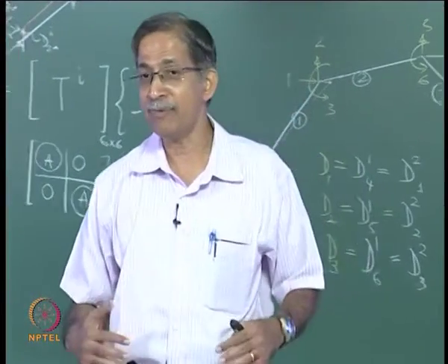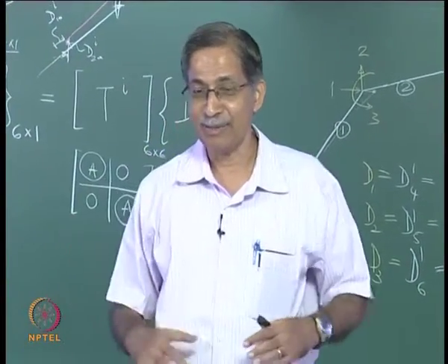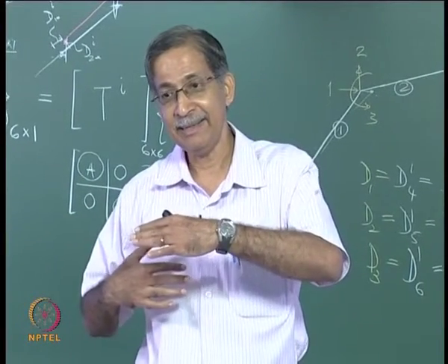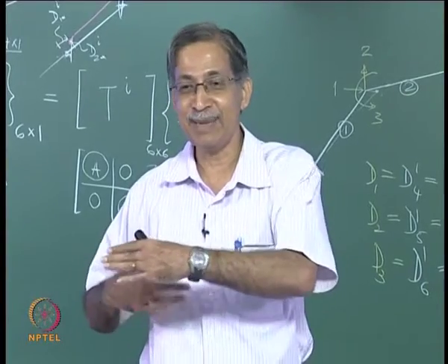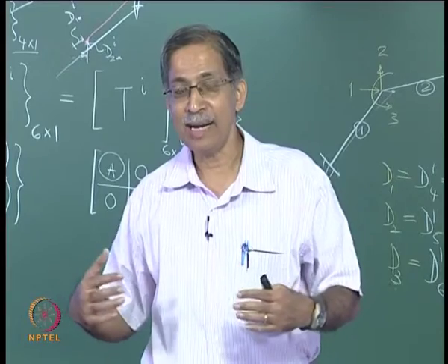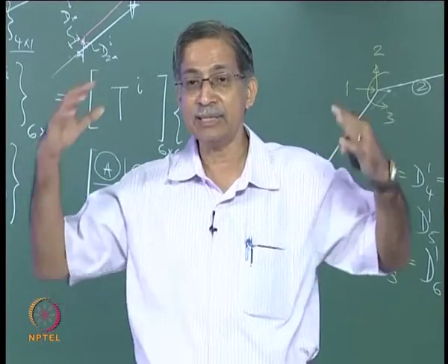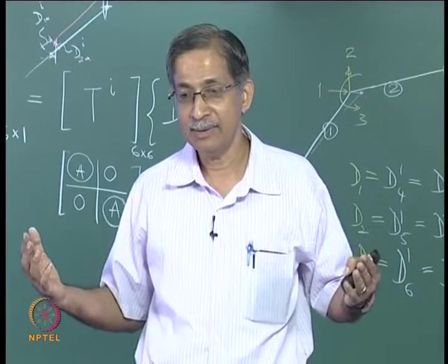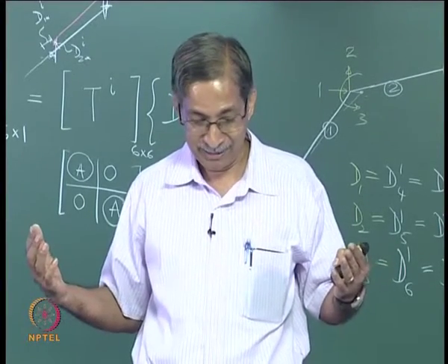I am now moving from state government to central government. I have got 3 states. All the 3 states have already been aligned. The stiffness matrices are ready. K1, K2, K3 are ready. How do I put up the big matrix? What is the size of the big matrix? No, for the whole structure. No, there are 12 degrees of freedom.